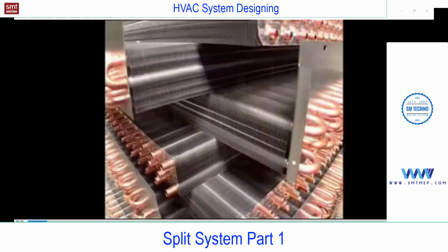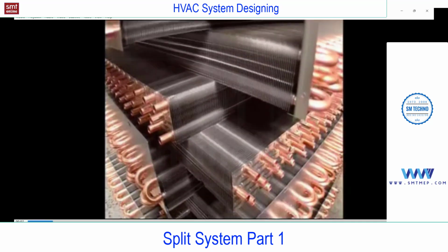So if the outdoor unit is placed in humid areas and it is aluminum, the life is going to be less. So in that case, even the fins you'll find are made up of copper or with an additional coating. That depends on the model. But from an interview point of view, the default configuration is copper tube with aluminum fins, for condenser as well as evaporator.